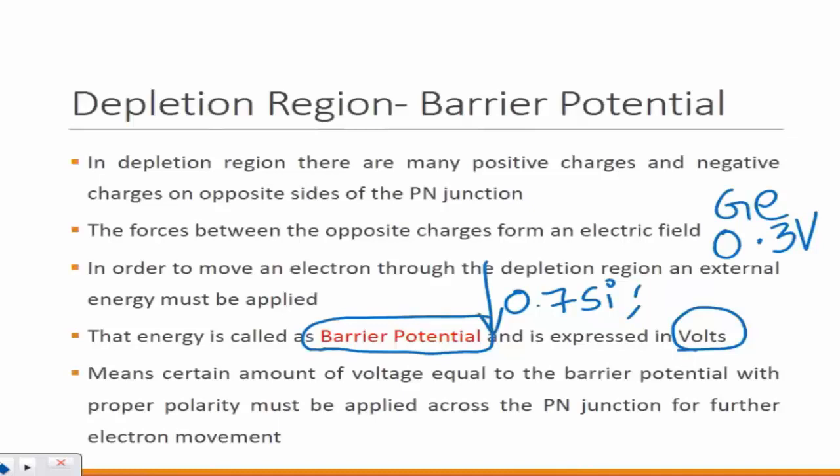So that's the depletion region versus the barrier potential. The depletion region shows that the region was depleted of the charge carriers. So that region does not have anything, in layman's terms. Barrier potential is the voltage. Potential means it's a voltage that is being developed across the barrier once you have the depletion region. And that will account for approximately 0.7 volts.